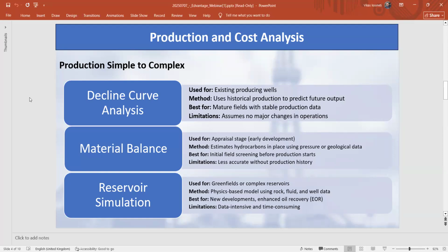You put in all the subsurface values: the depth of the reservoir, the porosity, permeability, pay thickness, and everything. Once you add them, the commercial software is designed so that you can literally see a 3D model of your reservoir. That's the main purpose of reservoir modeling. And once you know this, you play around with numbers to see how they would affect your overall production.